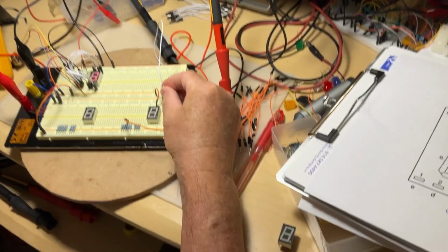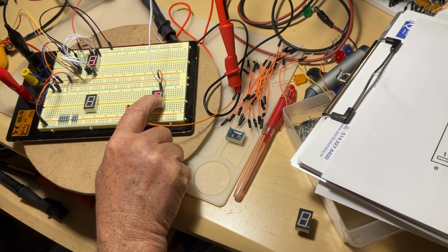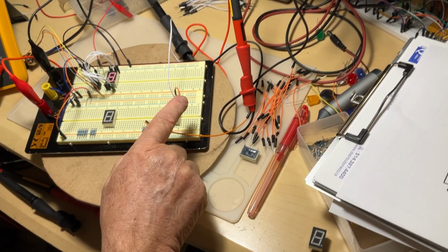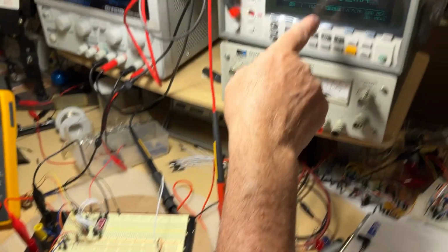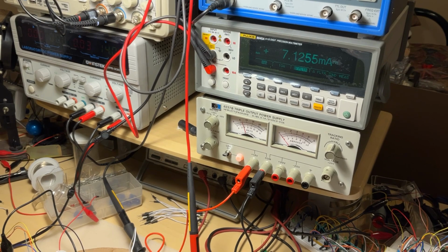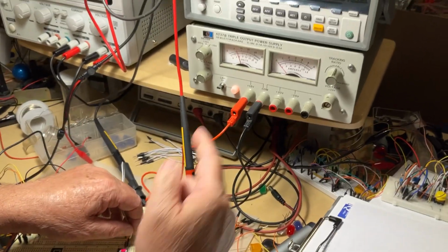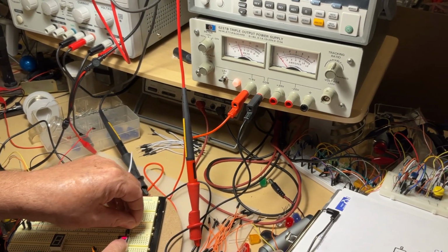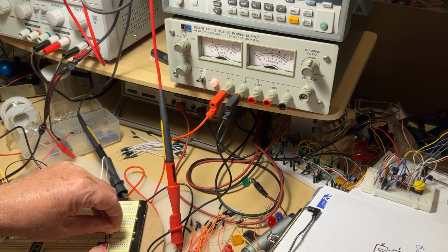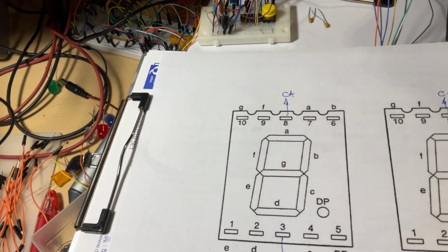A should be on 7. I can see here it is 7. And the reason I make that connection is because I want you to see the amperage coming on the segments to show you that all the diodes are identical. So it's around 7 milliamps. If I move it here, B should be on 6. I just move it one pin. B should be on 6. 6 is representing the B.